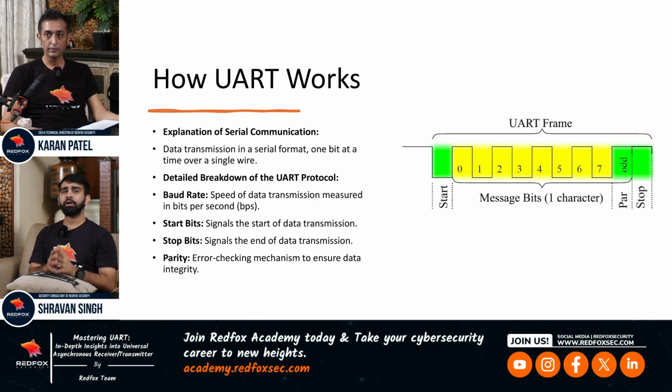Okay, in UART, if you check, there is a frame. In a UART frame, there are a total of 4 sections. If you compare it with other serial communication protocols, there is already a clock. It depends upon the clock how it starts and where it starts. The clock generates a pulse so that we can know when the data is transmitting and when the data is receiving. But UART is unsynchronized, so we do not have a clock, and because of that we are unable to know where the data starts and ends.